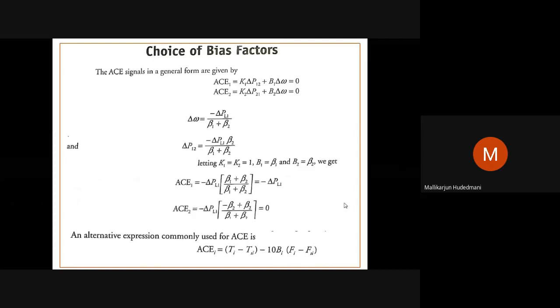In line with the discussion on AGC in interconnected areas, we were continuing to understand the role of primary ALFC and its failures when two areas are interconnected by a tie line, trying to deliver the change in loads of area 1 and area 2 respectively. Both the areas were responding to the change in load. That was not a desirable feature, and that was solved by adding a supplementary loop to the old control system.